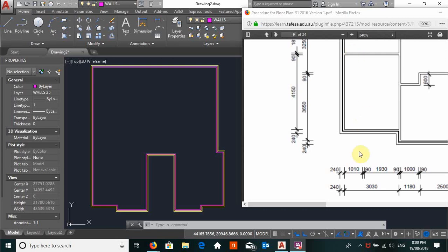And again, where it has an indentation there, we are going to place a cupboard eventually, but to create that, that's 600. So from that line we offset it by 600, and again offset by 90 for the stud. So let's just do that.